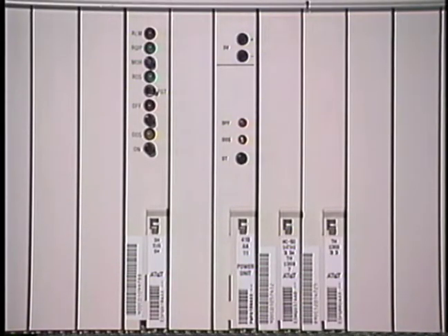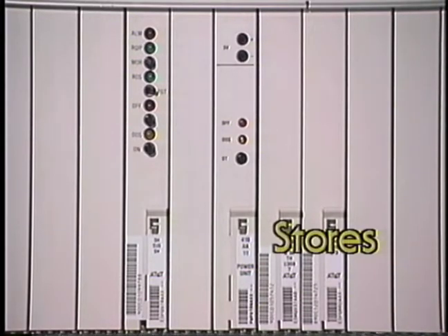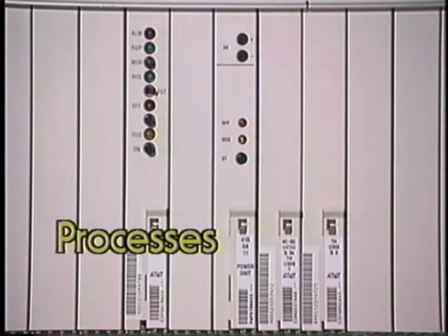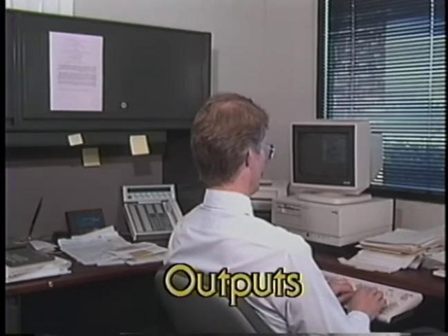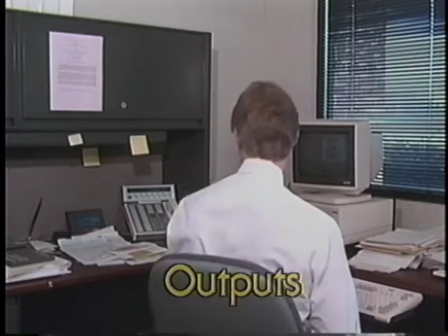The processor receives the telephone number and stores it in temporary memory. The processor then processes the number to determine what service is required and how best to provide it. When a line is selected for the called party, the processor outputs a ringing signal to alert this party, and an audible ringtone is sent back to the calling party. When the called party answers, the computer sets up a two-way path so both people can talk simultaneously.